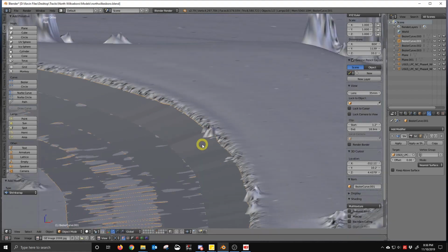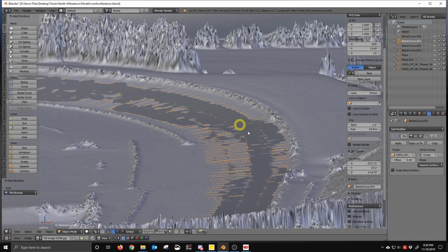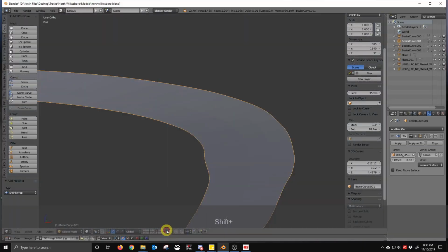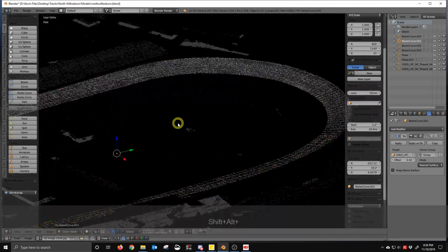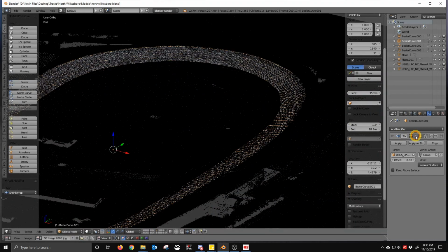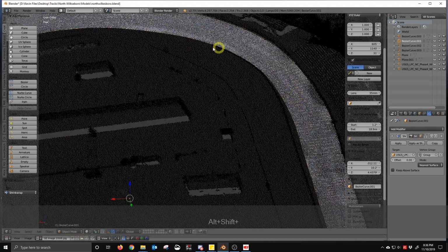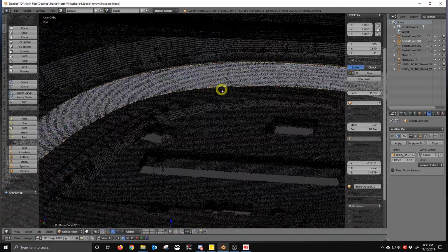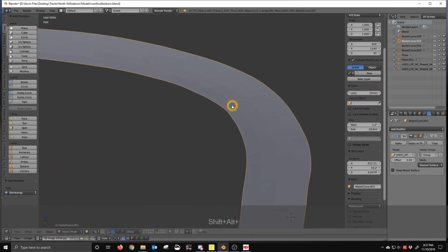So we're going to go over to the vertex group and select the group we made, and it's only going to care about the center pieces. It's not going to care about the edges. So the edges will be left alone as they were before, and the center will be nicely shrunk down to the mesh, and you can see now it matches much better all the way around the track. You can see on and off the difference between the center and how it was with just the edges lined up. So that's pretty much as good as we're going to get. You see it's pretty smooth.